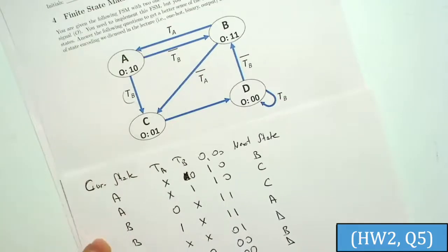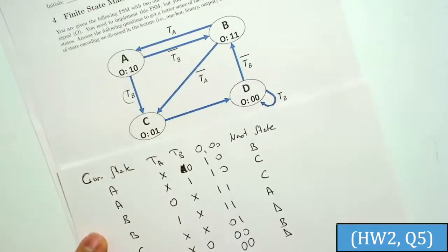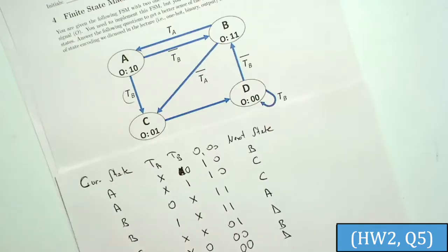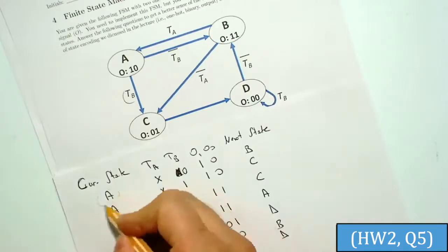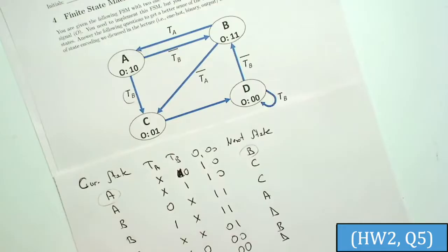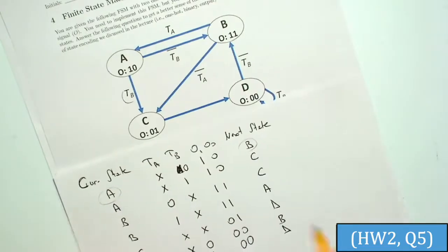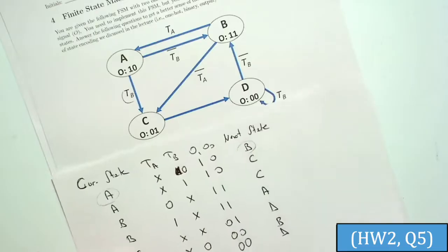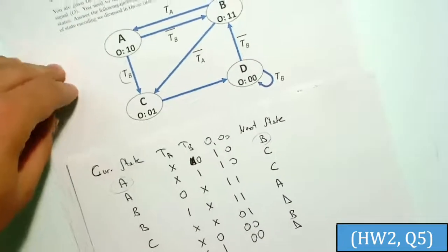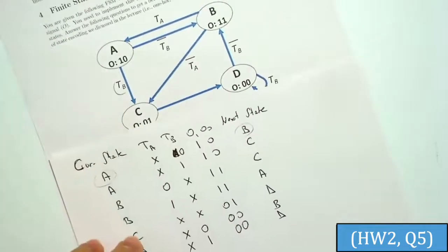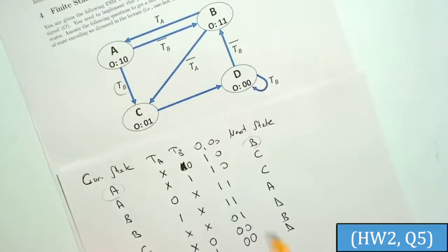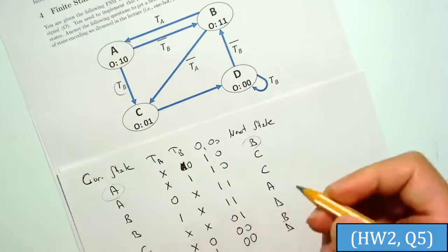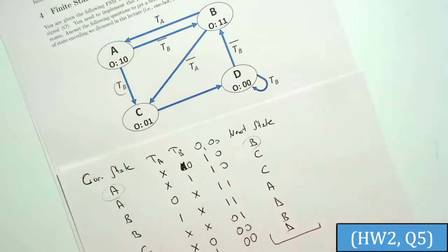Okay. So this truth table is a higher-level truth table, I would say, because I don't have the bits for the current state and the next state, but I have the explicit bits for the output and the input bits. For the following three questions, what I'm going to change is only the way that I represent the current state and the next state.